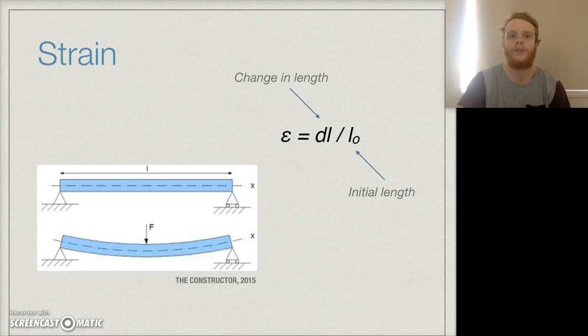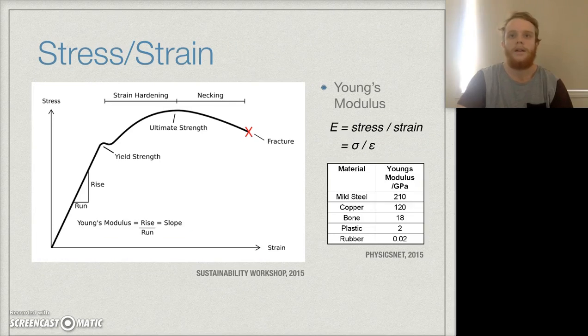Moving on, strain is the resultant deformation of an object due to stress. This is commonly seen, for example, when a beam fails and it flexes before this. There are two main phases of strain, which are elastic and plastic deformation. Within the elastic phase, the object is free to return to its original shape.